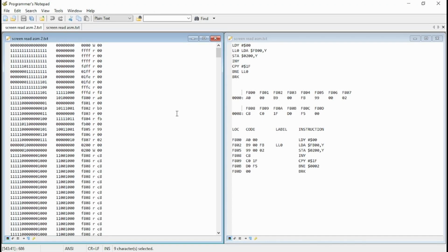Okay, so on the screen here I've got the outputs that we saw earlier from the breadboard and the Arduino, and then I've got here just the code that we can talk through as it's executing. So the first thing to describe is what we actually see in this file. This is the binary address line, this is the binary data line, this is the hexadecimal address line, and the hexadecimal data line. And then this here is telling us if there is a read or write cycle going on. So that's really useful as to what the CPU is trying to do.